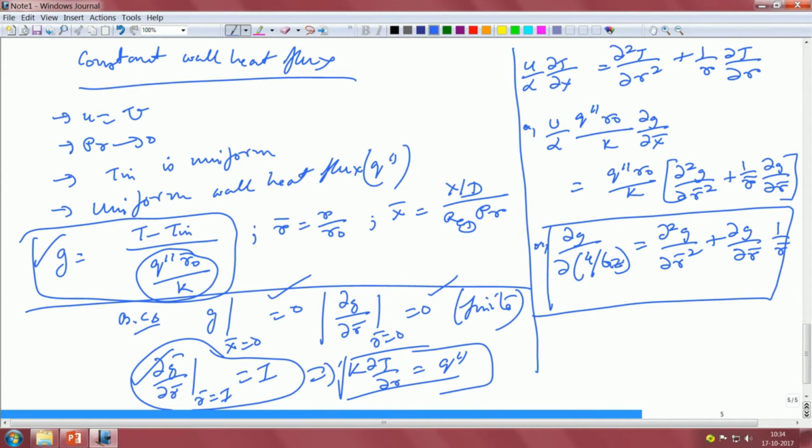In this particular lecture we have covered the uniform slug flow, in which we have shown that though this is an unrealistic situation, for all practical purposes the boundary layer remains small throughout the entire span of the pipe length, so perhaps this is not a bad approximation. It might over predict the Nusselt number by a little bit, but that is okay because your analysis is very simple, and it almost represents a transient heat conduction equation, as we saw, where the time varying conduction term is basically the axial conduction term.